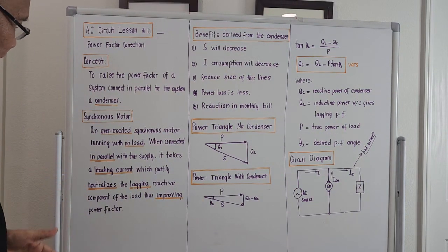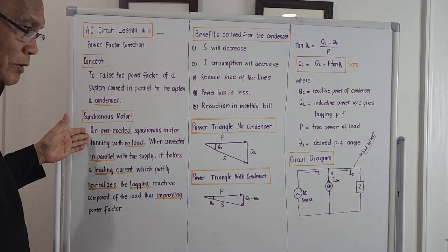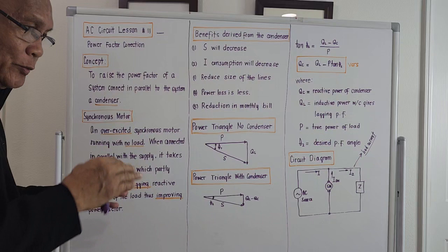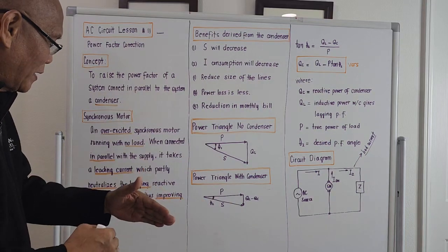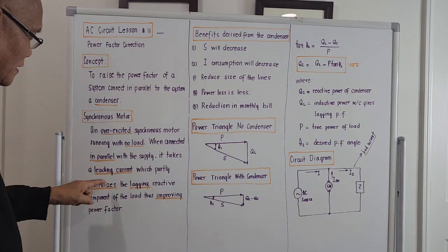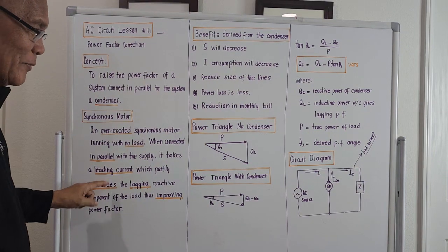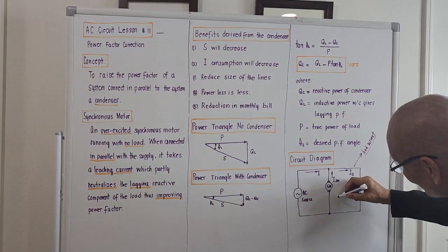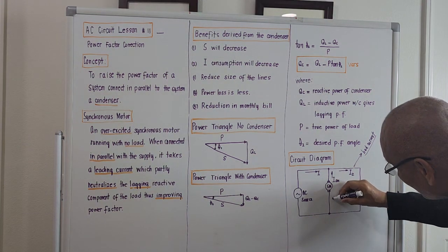Meaning to say, it is an overexcited synchronous motor which runs with no load and produces a leading current. So this synchronous motor here will produce a leading current.